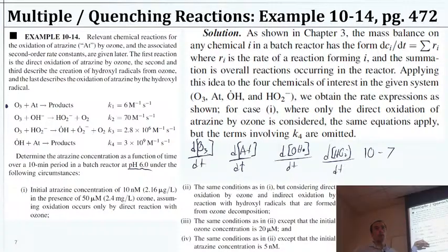However, we do need to calculate the other pieces because they're taking away some ozone. So what we're going to do is calculate, in step 1, the atrazine that is destroyed according to this reaction based on how much ozone it starts with. For the first second, let's say, we could do 0.1 second at a time, we could do a second, we could do 10 seconds.